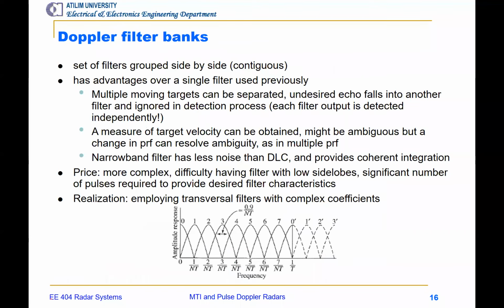Okay, another filtering technique is to use Doppler filter banks, where we have contiguous filters that are placed side by side over the band in which we expect the Doppler shift, and they are overlapping.